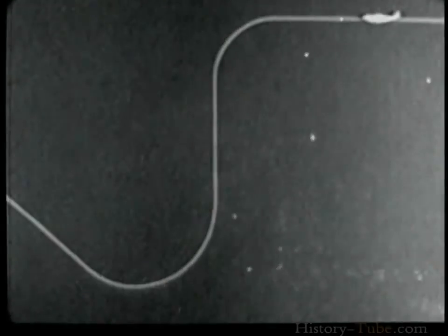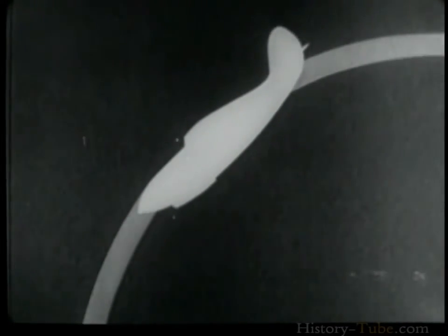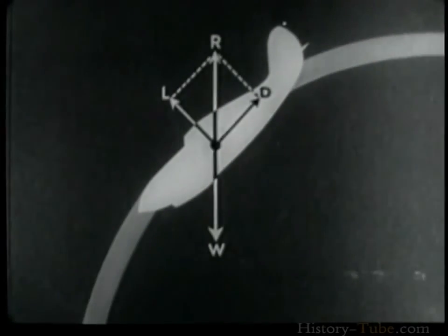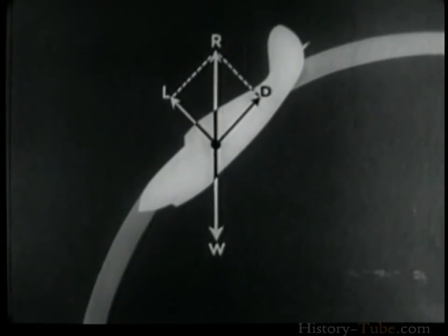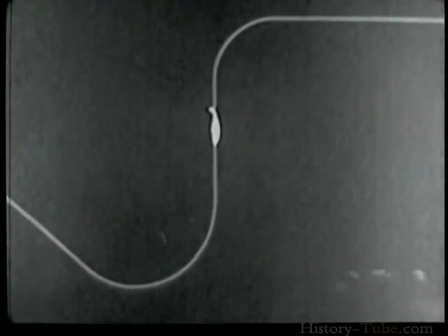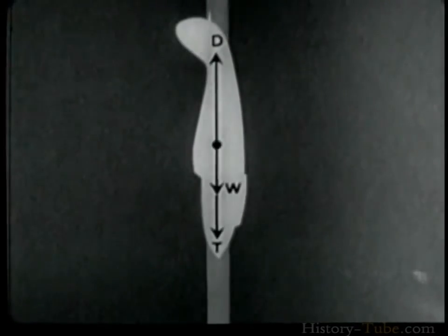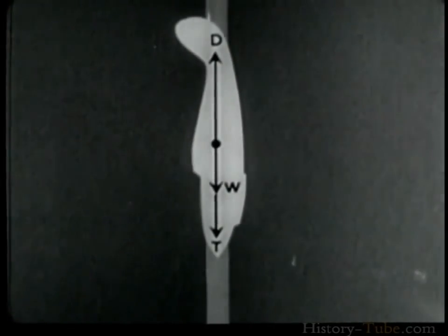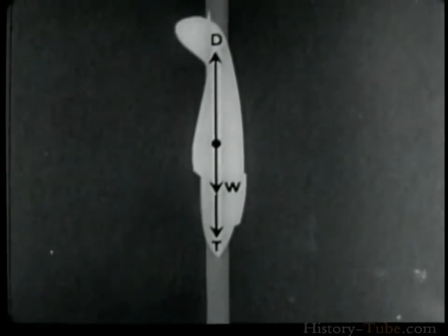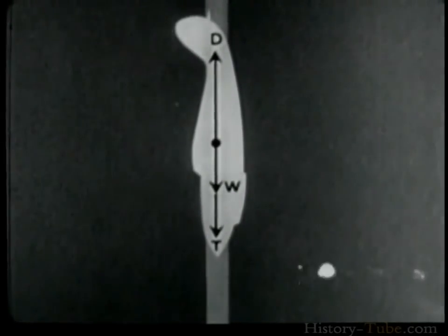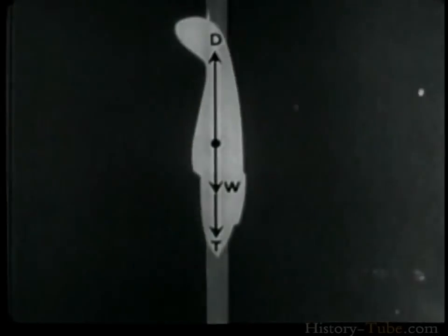Consider the case of an airplane flying horizontally at a small positive angle of attack. As the controls are set to put the airplane into a dive, the angle of attack decreases and the speed increases. Lift decreases, since in this attitude the weight of the airplane is opposed by the resultant of lift and drag. As the flight approaches the vertical, speed increases until the terminal velocity is reached in the so-called vertical dive. In this condition, lift is 0, and the weight of the airplane plus its thrust is opposed by drag alone.